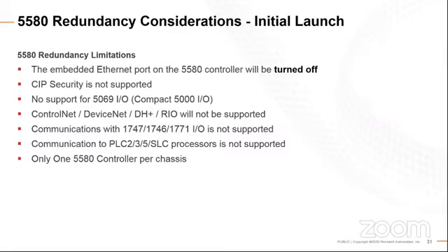And one other change that may or may not be a little different than what you guys have been used to is, generally speaking, in an L7 style design when we had two separate chassis, one of the options that we've had for quite a few years is the ability to tie in two controllers. Now, in a PlantPAx style design, we will tell you not to do that.